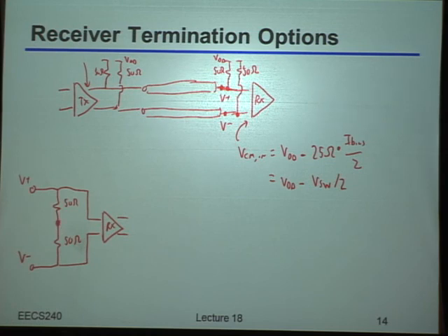Okay, so you said that you could bias this to some common mode voltage. That is true, although we have to be a little bit careful in that if you really were to do exactly what I drew there, what's perhaps bad about this? Exactly. You're sending DC current all the way from here into this point right here. You're absolutely correct. There is going to be DC current flowing through there. But now, obviously, if this is not VDD on both sides, the impedance of that might not be sufficiently low. But you're absolutely right. The same thing is happening in both cases from a DC current standpoint.